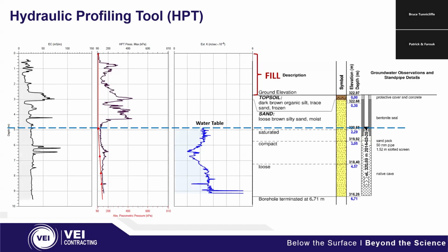Now you'll notice that our water table was just around 5 meters, and when we account for the elevation change, we were actually pretty close to where they measured water in the groundwater monitoring well adjacent, MWX. Very good agreement when you consider all the seasonal fluctuations that could happen, especially in a sand.